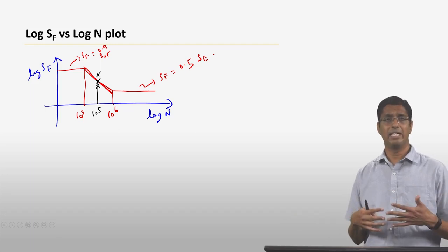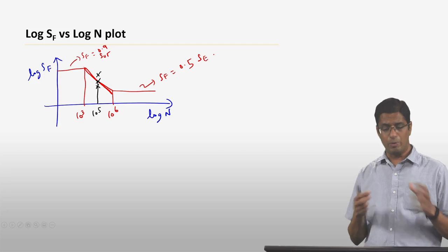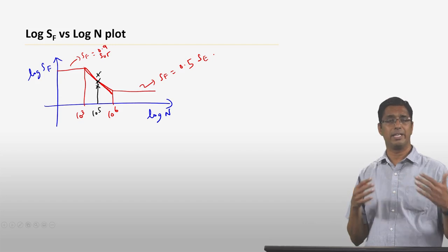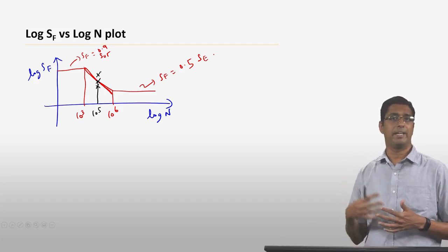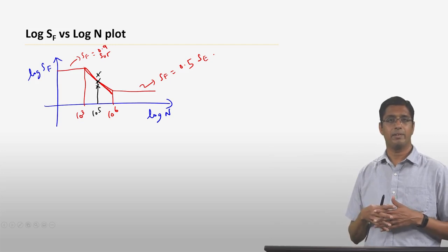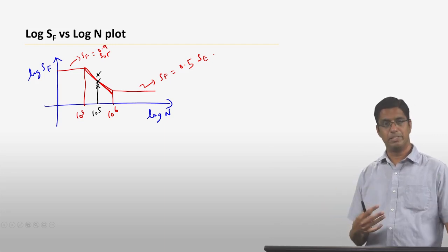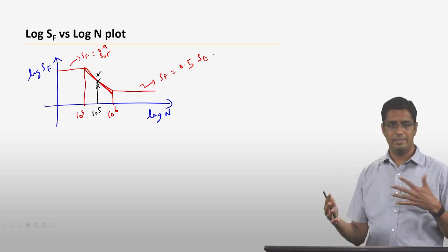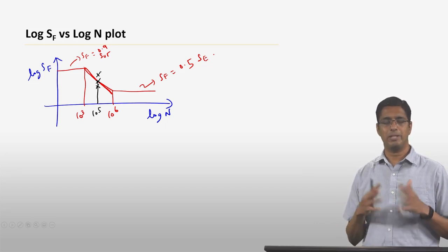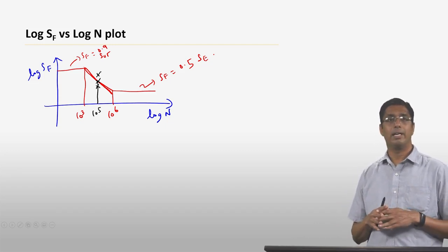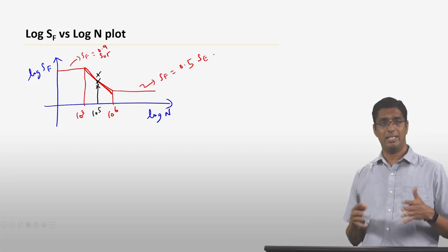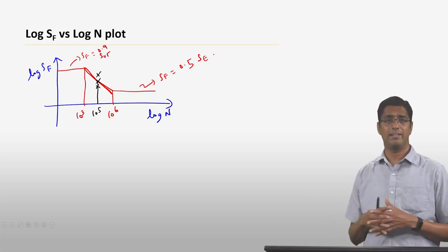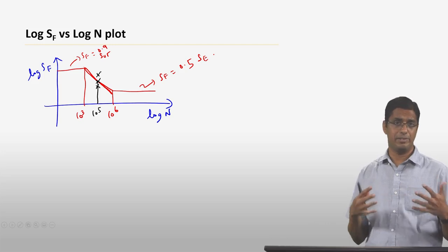So essentially, fatigue is not a very precise phenomenon, but all these diagrams give you is a sense of where you can expect things to fail. If you say, okay, I'm going to apply a cyclic load of 50 MPa, then you can say this material is probably going to fail somewhere between 50,000 and 70,000 cycles. That's the amount of precision that you can get. So that's something that I want you to keep in mind, that these SN curves have a lot of scatter, and these are mostly experimentally determined. There's no theory or formula that you can use directly to obtain them. Many of them are just done empirically.